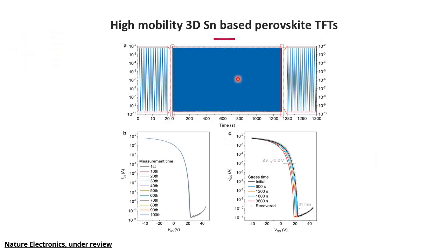The final 3D tin-based perovskite transistor shows very nice switching behavior, and under strong bias stress conditions the threshold voltage shift is relatively very small. One interesting thing is that the transistor returns to its original state very quickly after the bias. We don't fully understand why this happens, but we mainly guess it is related to the defect tolerance of our tin-based 3D perovskite transistor.